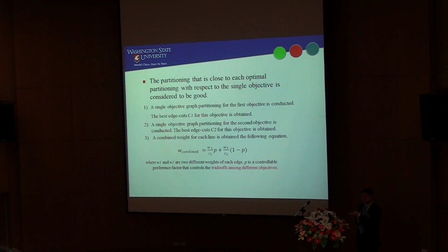When you partition, the objective is to make sure that after partition, these partitions will be able to survive on their own, which means the supply and demand for each partition should be more self-sustaining. That means the exchange of real power and reactive power between partitions should be minimized. So we take a real power partition and a reactive power partition, and somehow weigh them together and create one partition that considers both.